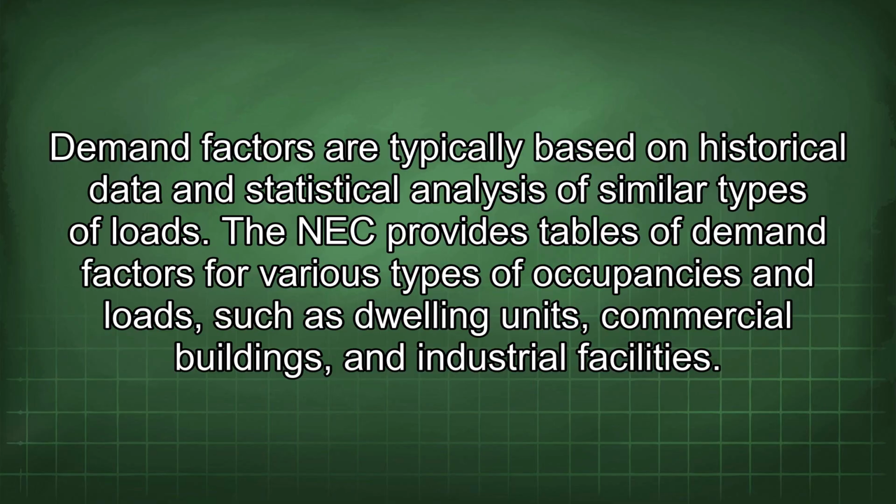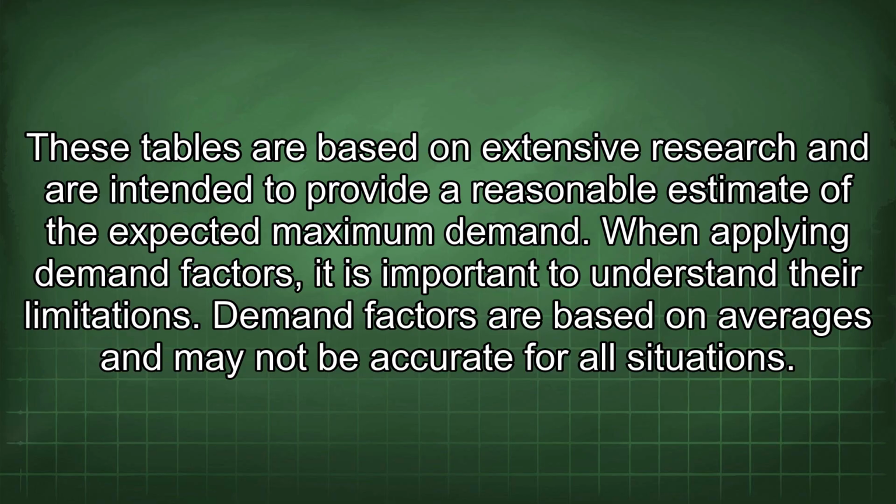The NEC provides tables of demand factors for various types of occupancies and loads, such as dwelling units, commercial buildings, and industrial facilities. These tables are based on extensive research and are intended to provide a reasonable estimate of the expected maximum demand. When applying demand factors, it is important to understand their limitations.